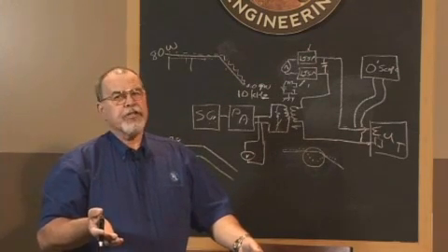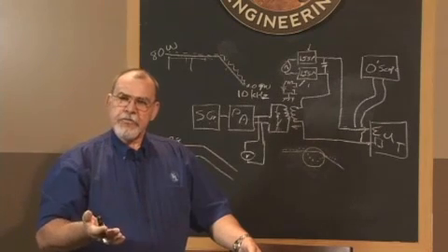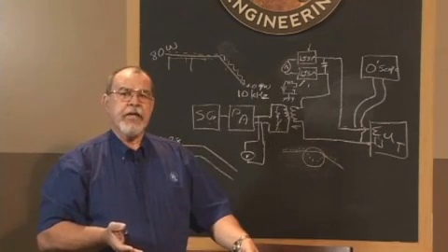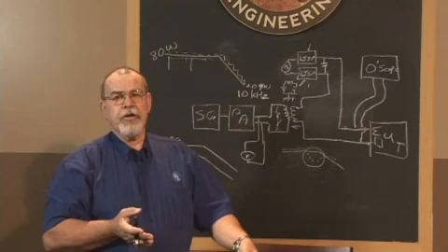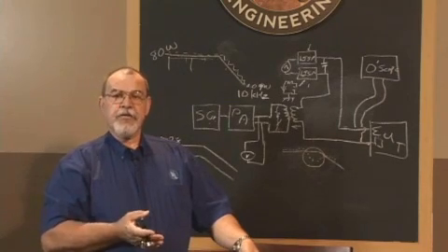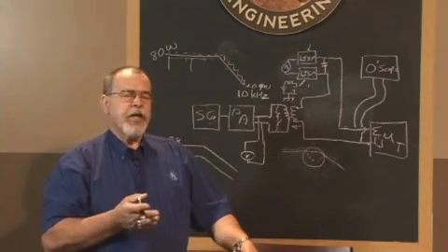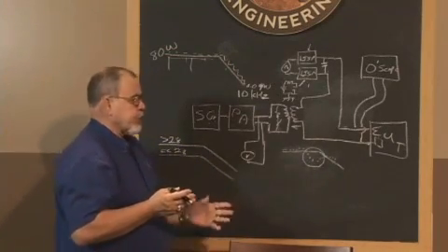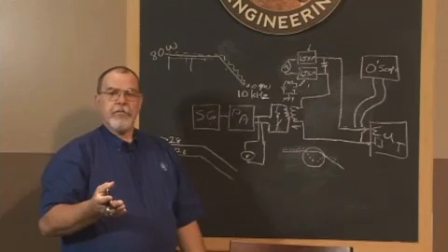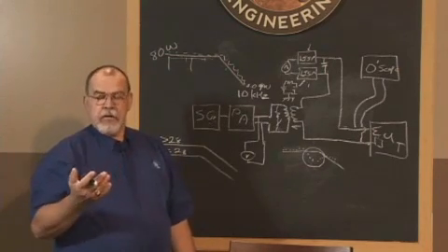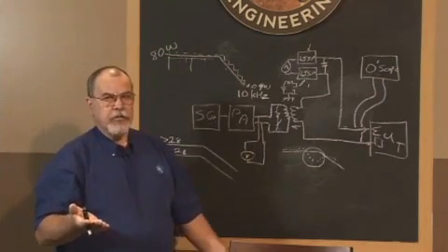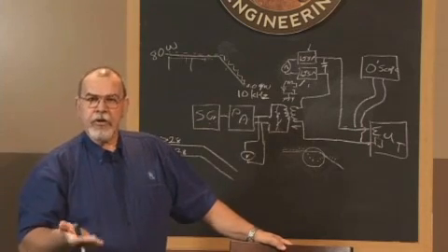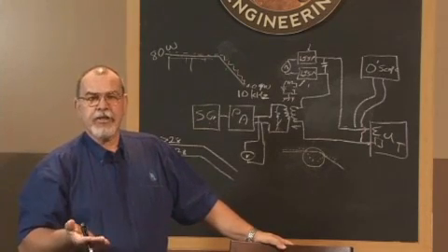However, if you start hearing speed changes, and this should be determined prior to the test in your planning element, what is the susceptibility threshold? What is the pass-fail criteria? Without knowing that, you don't know when this test is being accomplished. So pass-fail criteria says if the fan slows, and how do we measure slows? We must have a monitoring system to let us know that the fan is slowing.